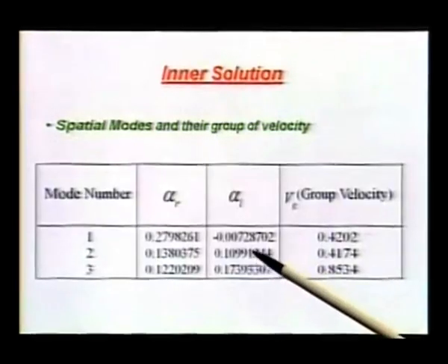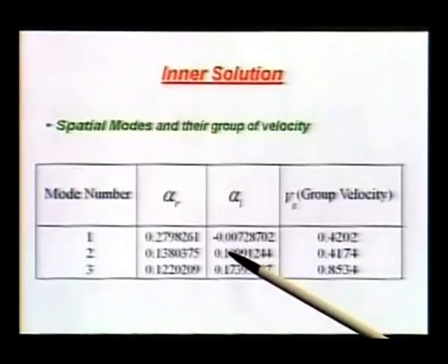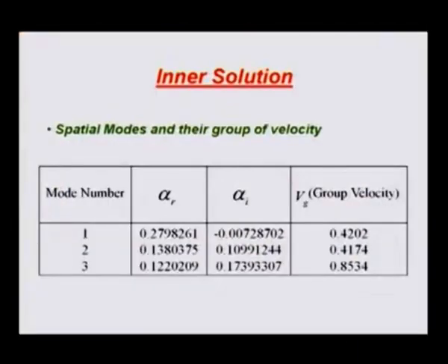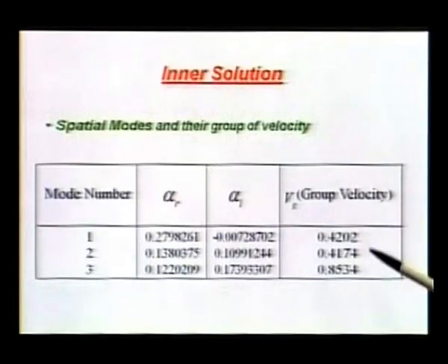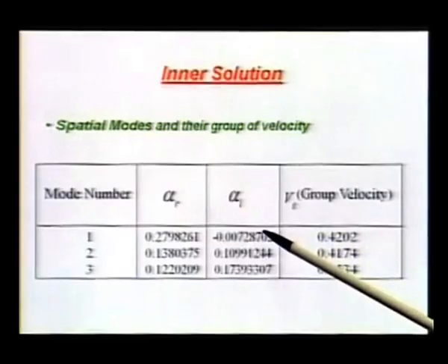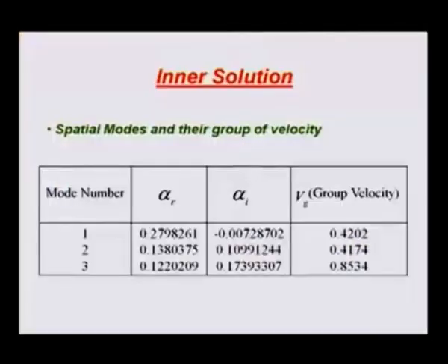These last 2, as you can see, come with a plus sign. So, if they were going downstream, they are stable modes. How do you find out which way they are going? Calculate the group velocity, and we calculated the group velocities. All of them are positive. So, they are all downstream propagating waves, and then this is an unstable wave, and these 2 are stable waves.